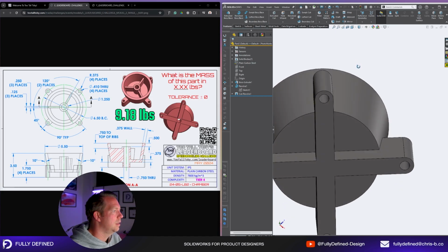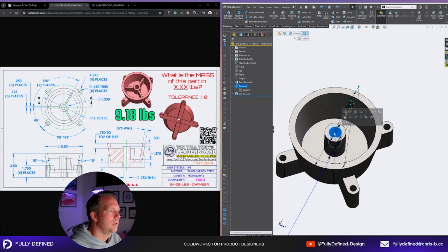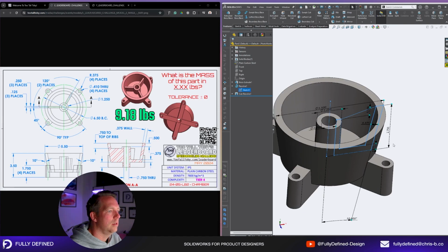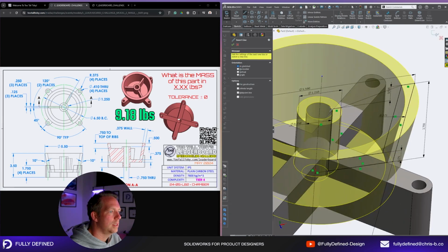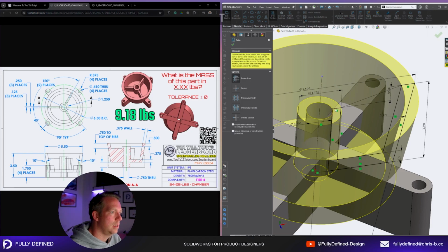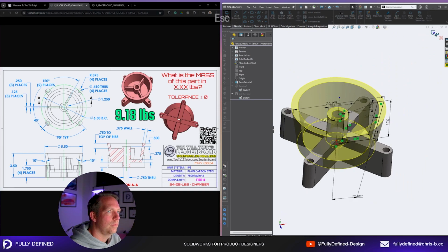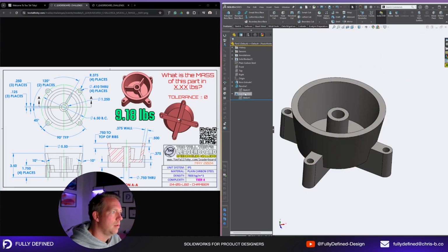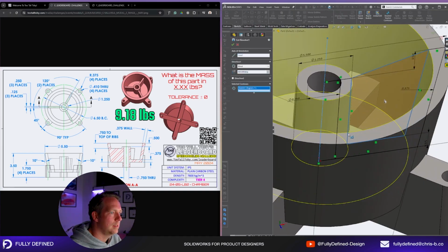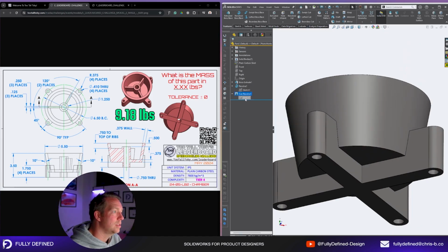And we do have to do that hole again here, or we can do that in that same revolve cut. Let's see if it likes it. Line there, scratch that. Extend this line and extend this line. Okay, contours are the same, but now in this cut revolve, I can select another contour, which is that middle bit. And I just want to get it going all the way through.